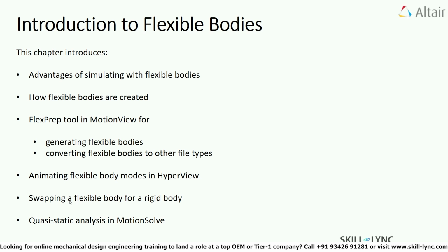In CAE, we should always aim at building models that are very close to the structures in the real world and try to obtain results that correlate well with the test results so that we can minimize the cost of physical testing in the industries. Finally, the analysis that we'll be using in this exercise demo is a quasi-static analysis. So I will give a small briefing on quasi-static analysis before we dive into the simulation.